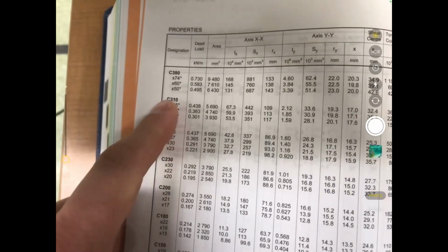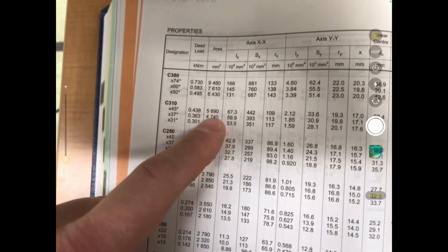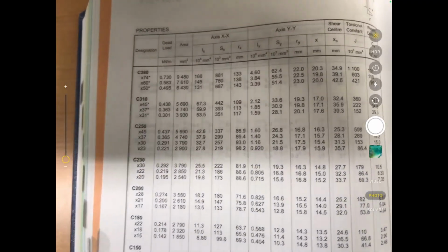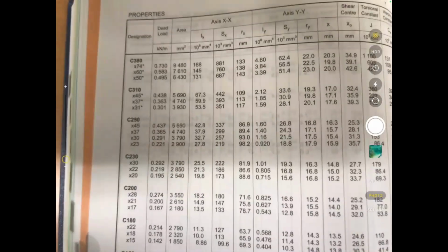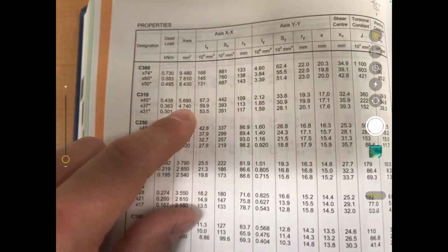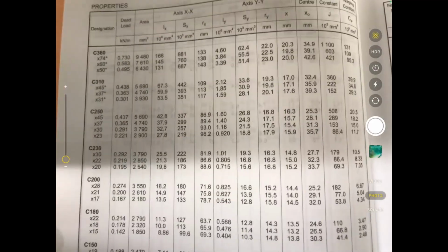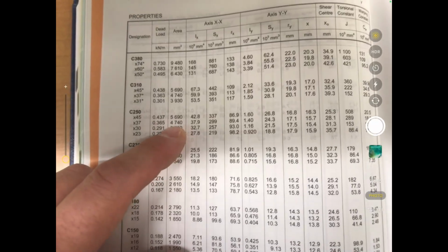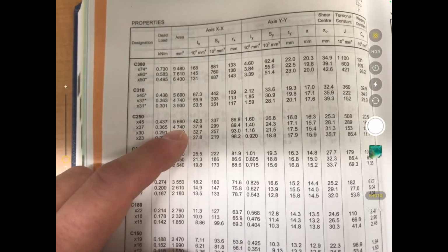That's pretty close for an area of the channel. And I already know that the values I use for NSF and SLF are probably quite conservative. So I'm actually going to pick one that has slightly less area than I need. I know that the fabricator, if they know how to do engineering, can make this work. I'm going to be short by like 2 or 3% of the area, but they can certainly make that work.